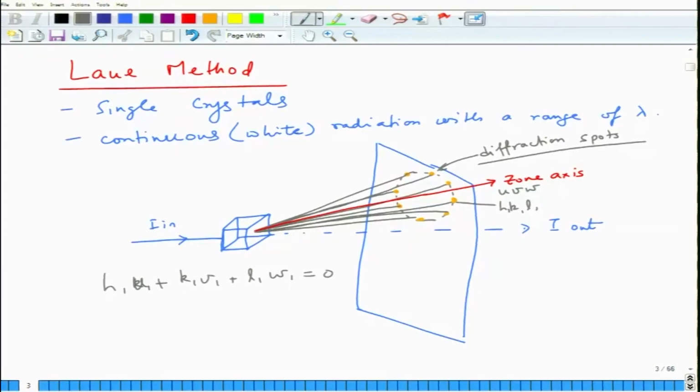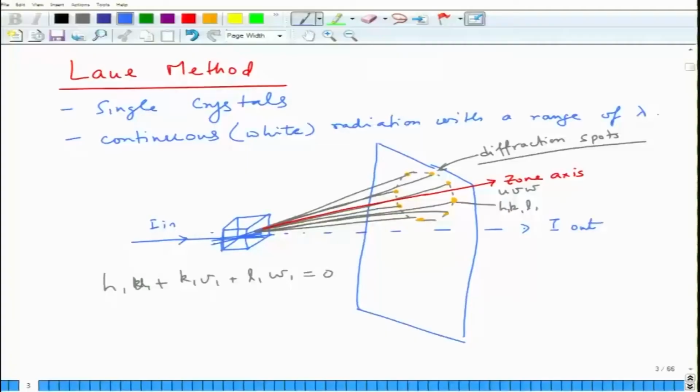So what basically it means is that you will have a zone, you will form a cone, and this is the transmitted beam. Typically, for most of these, the plane orientation would be, so if you combine these two lines, some plane would be like that, some plane would be like this. So planes will have different orientation, but not all planes, only those planes which have appropriate interplanar spacing and angle satisfying the Bragg's law. That is why we use variable lambda,